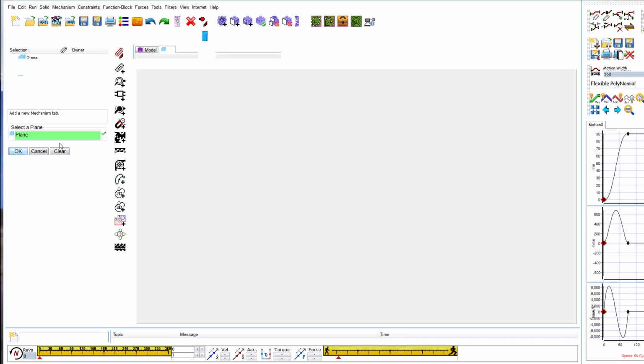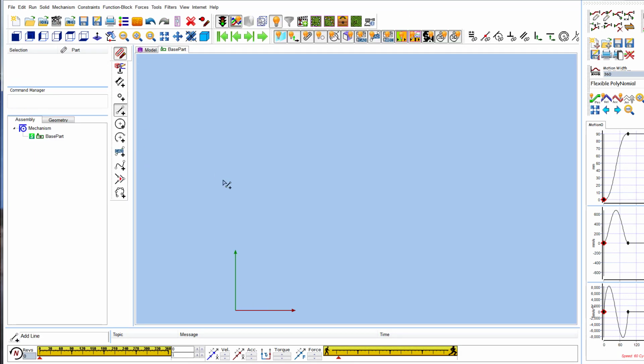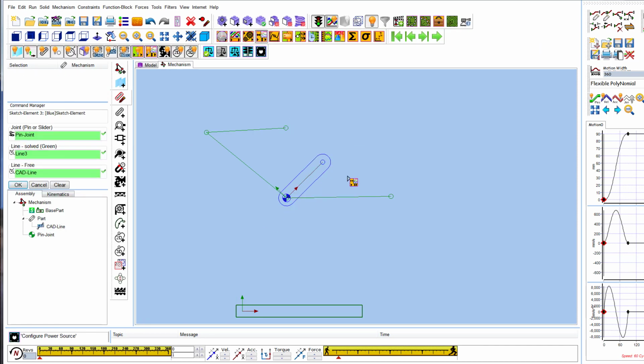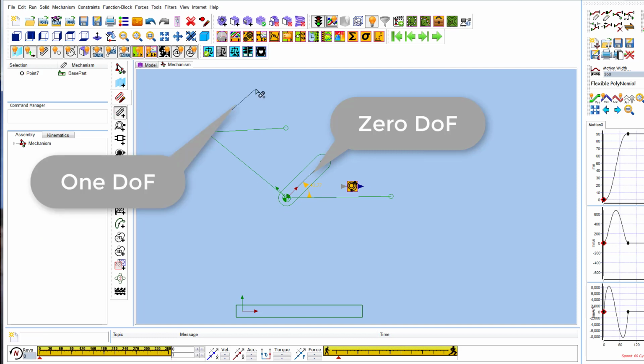So now I will set up a simple gear pair to demonstrate. First I will add 3 lines. The linking line is the one we need to dimension. Then create a 0 degree of freedom rocker by adding a part pinned to ground and driven by a motion dimension. And finally a part just pinned at the other end. These 2 parts will carry the gear wheels.